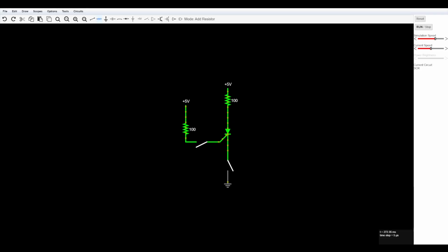All right, here we have a silicon controlled rectifier. We're going to start the current going through it from anode to cathode. We're going to turn on the switch to turn it on. Now we're going to turn off the switch and the current is still flowing. Turn it on, turn it off. So 344 millivolts, turn it off.